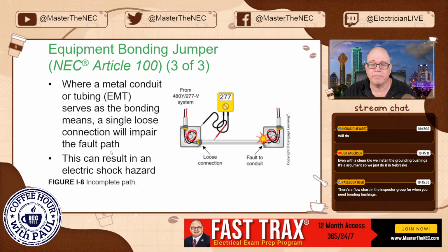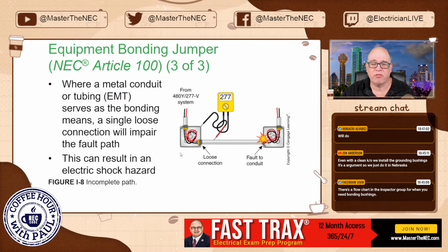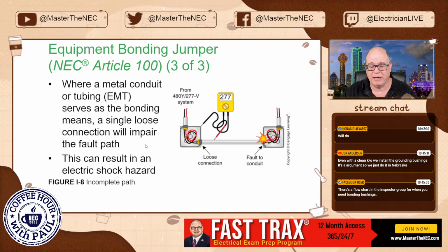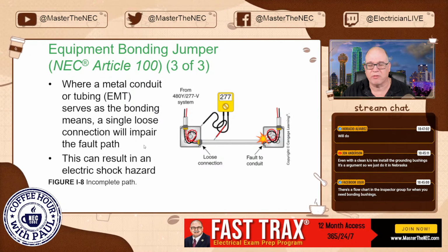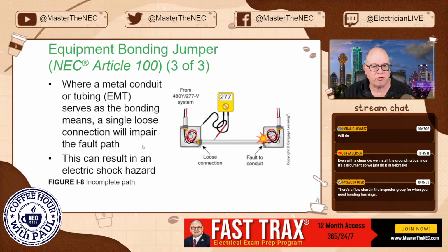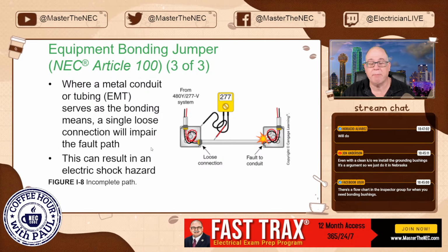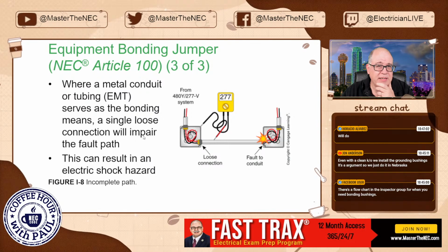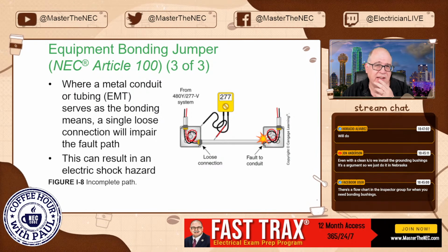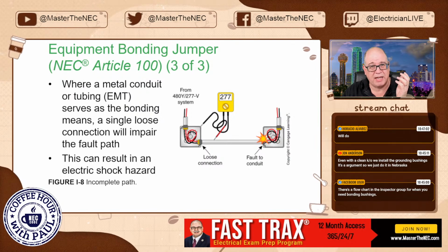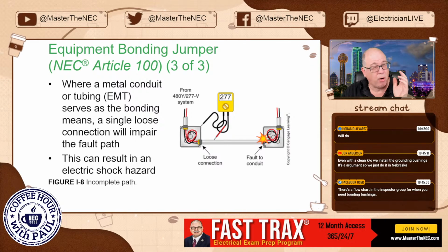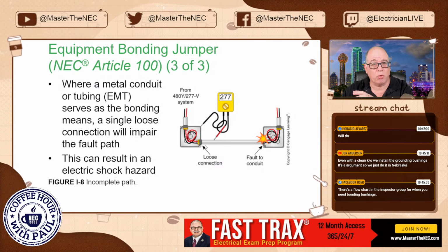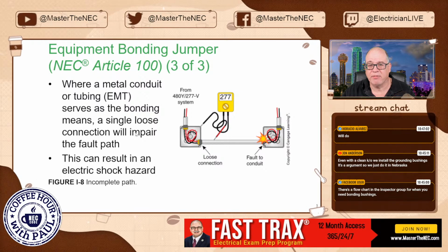So this can create a hazard. That's why, please, if you're the supervisor, make sure that you harp on your guys and gals to make proper terminations, okay? Properly secure the couplings, properly secure the connectors. Set screws have to be done, okay? That type of thing. And believe it or not, did you know that even the set screws on a coupling have to be torqued? I bet you didn't know that. There's a NEMA standard for that. They have a torque value, believe it or not. All connectors have a torque value. I know we all follow that, but they do have a value. And this is one of the reasons why, to ensure that you're going to have that effective ground fault current path.